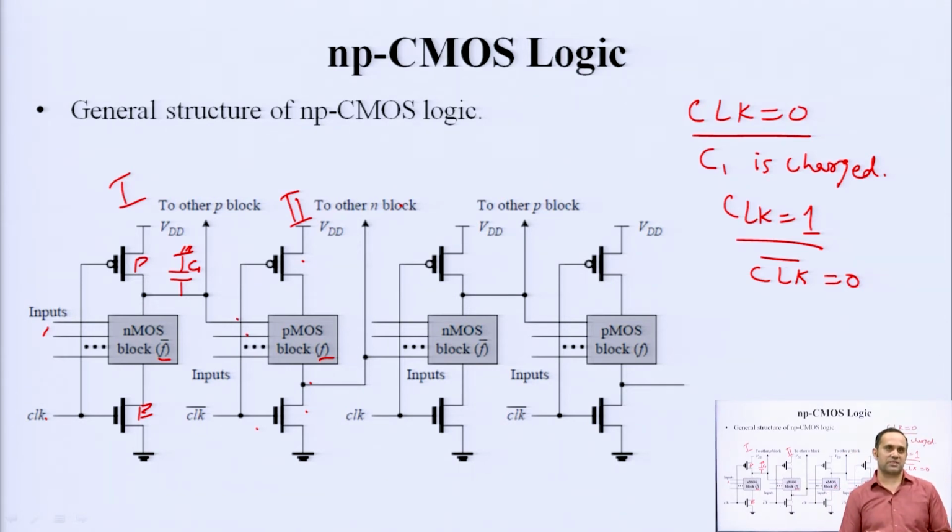One is in pre-charge, another is evaluating; when another is pre-charging, the next stage is evaluating and so on. This way they are not charging or discharging together. Whatever is being transmitted from stage 1 is saved, isolated from the next stage. So the high output of stage number 1 does not affect whatever is happening at stage number 2. Here you take the output of stage 2, let us call it C2, capacitor C2, and so on.